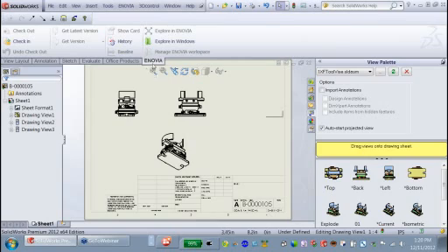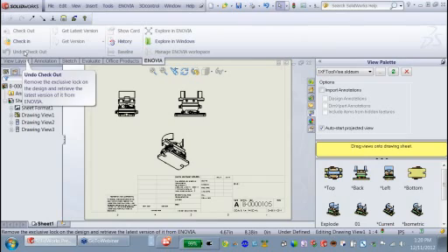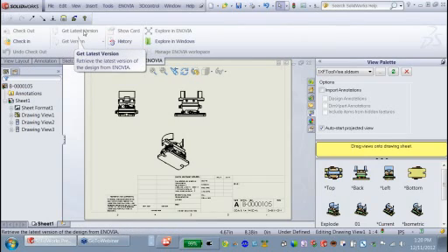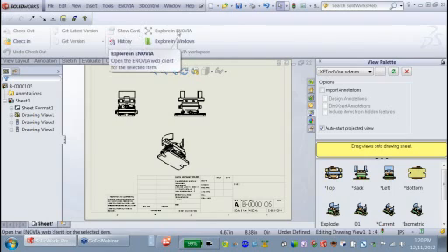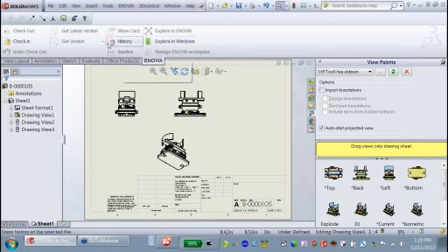As I said, there's a very short list of capabilities that are put in front of the user, because we don't want to burden them with all the broader functions of the PLM system. Check in, check out. You can undo what you've checked out, and as we already saw, we can get the latest version if someone else has updated something we're working with. We can even get an explicit version, as well as look at the history of all versions of information. Beyond that, we can explore it in the global web-based system as well and do further manipulation of design data beyond the user's normal SolidWorks design experience.